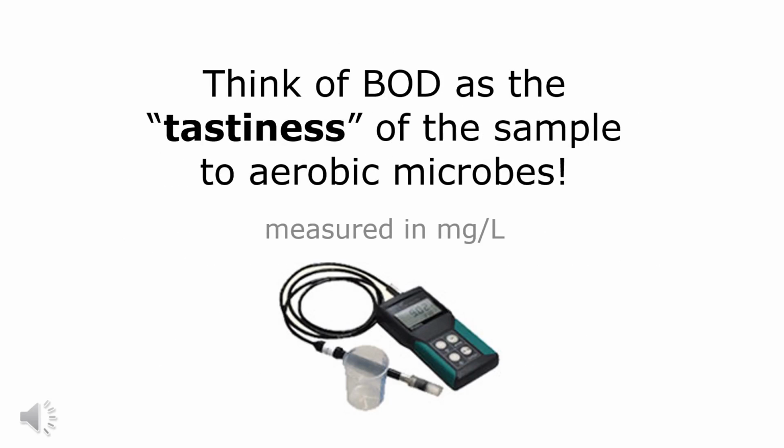From now on, when you hear the term biochemical oxygen demand, I want you to replace it with the more easily understood term microbial tastiness. A sample may not be tasty because it lacks growth factors, it's a thin gruel, or because it is toxic. The device at the bottom of the slide is a dissolved oxygen meter used for determining BOD.